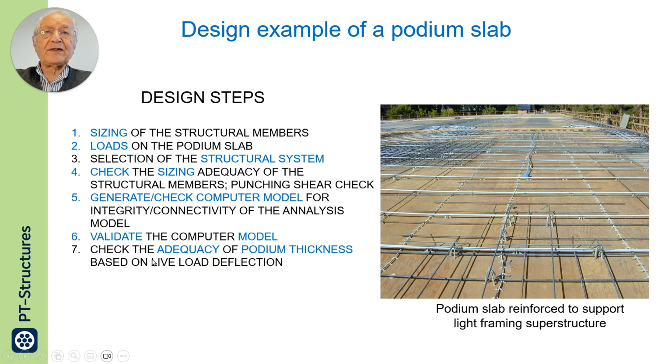7, we check the adequacy of the podium thickness based on live load deflection. Next, before moving forward to design of reinforcement and post-tensioning and so on, we check the sizes. We check really the thickness of the podium slab to make sure that the material selected and the thickness can lead to a design that meets the code requirements.